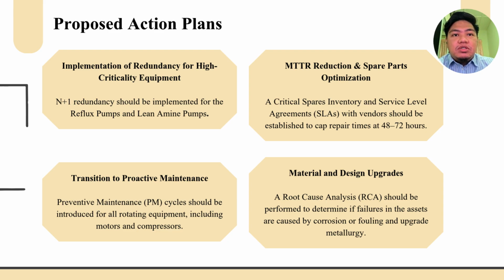Preventive maintenance cycles should be introduced for all rotating equipment, including motors and compressors. Predictive maintenance, such as vibration analysis, should be implemented for the expander compressor and residual gas compressor, so that the long duration corrective maintenance downtime is replaced with shorter planned outages by addressing potential failures before they occur. And lastly is the material and design upgrades for asset integrity.